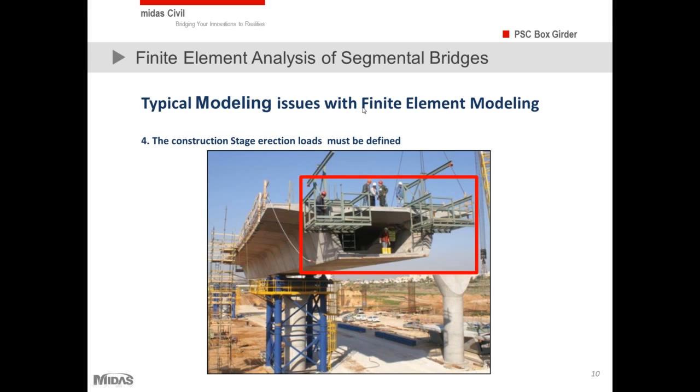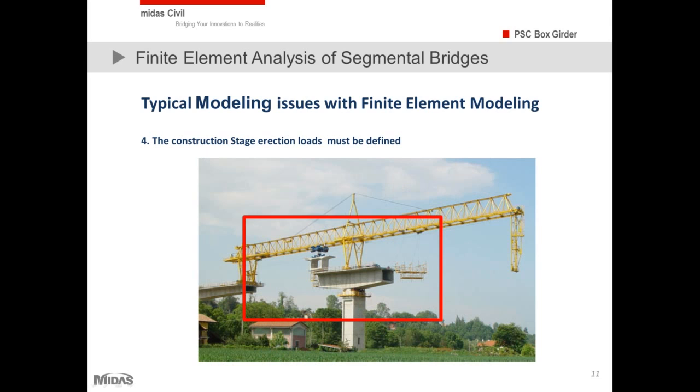This is again difficult to do in any finite element analysis software, because as the stage increments, these additional loads have to be defined at different locations. If we just talk about a balanced cantilever bridge, as you keep on adding each new segment, the additional load will keep on moving from one location to another. So we need to simulate this particular loading type. And once again, these are the erection loads.